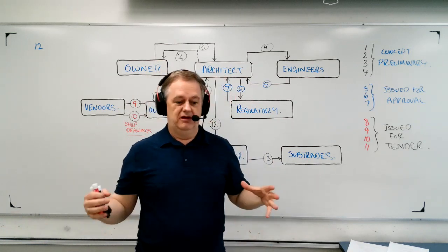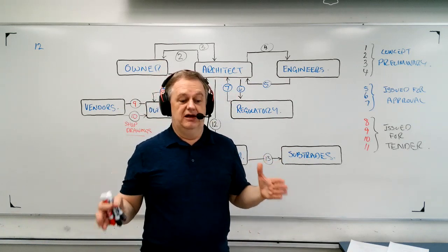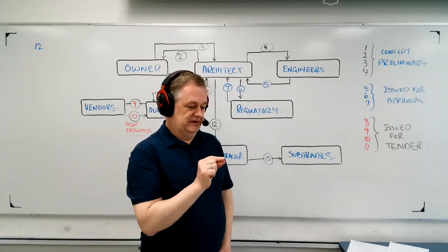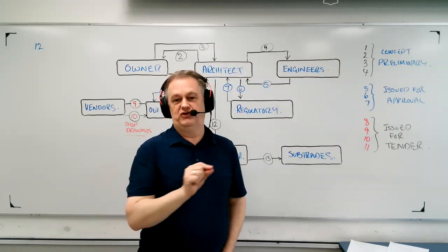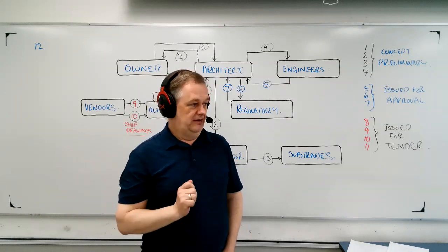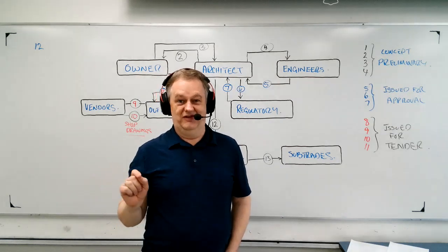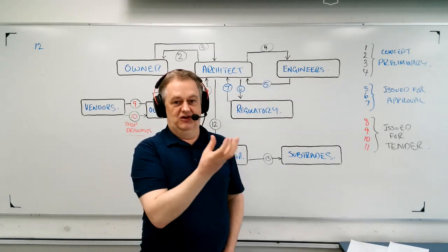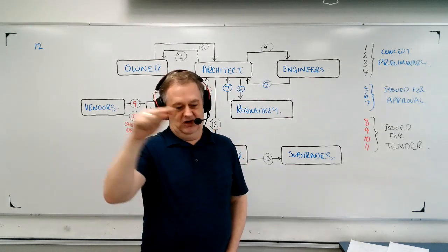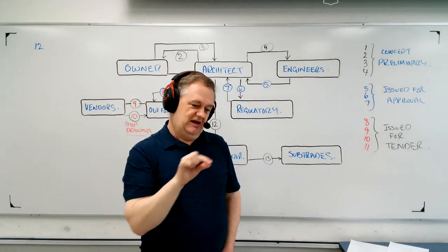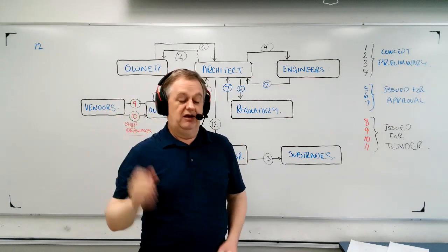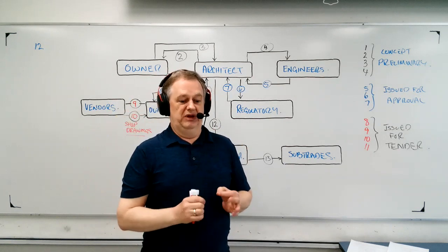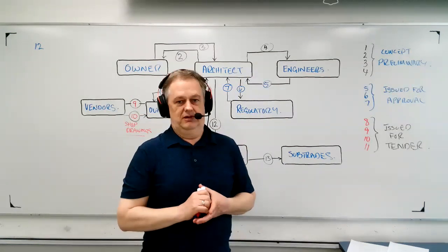You're going to do something, and then there should be a nice clean set of prints exactly for the purpose, and you should be saying, now, when I went to run this conduit that was shown on the print going down this hallway, there was actually an air duct right in the way. And so I actually had to jog over. I had to put a junction box, and then go past it, okay? So you draw that in, you draw the junction box, and you move it on. And what is that drawing called? Well, we call it an as-built, or the way you actually built it.